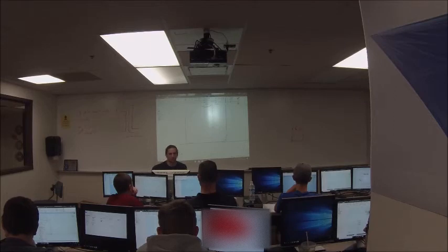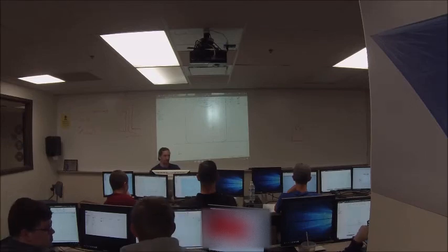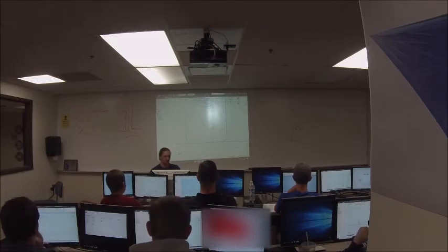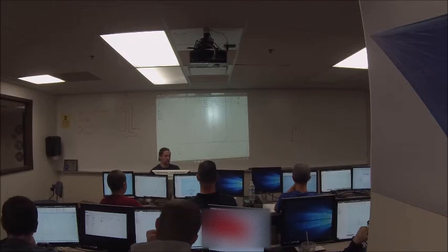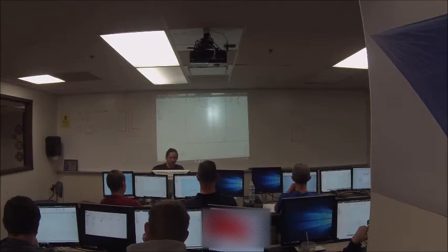So let's do that real quick. I can go in, delete the equals constraints. Now you'll see this line over here, I'm gonna hide my constraints again. This line turns purple, right? Which means it's now not constrained. It can change size at will. So now I can just click a dimension, drop a dimension down, click on the arc, place the dimension down, and make this a 1/2 inch radius if I want to.